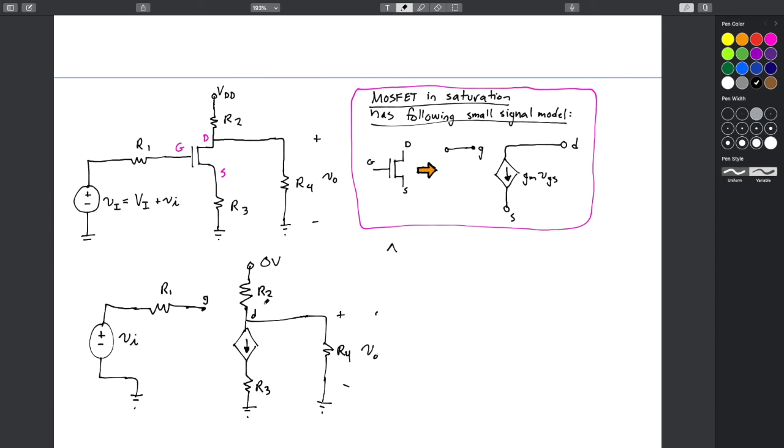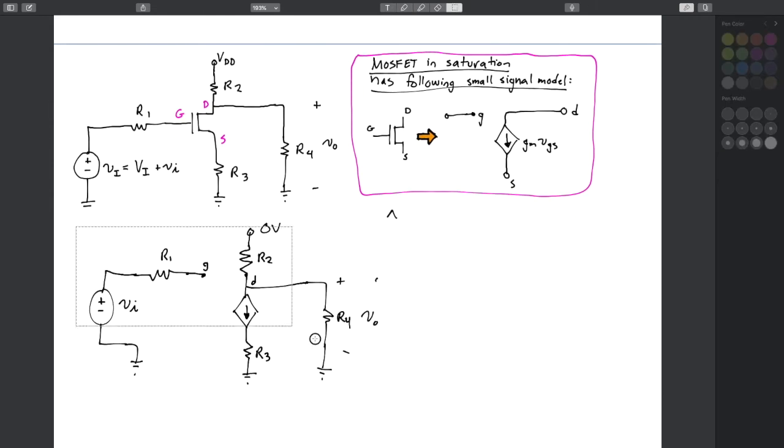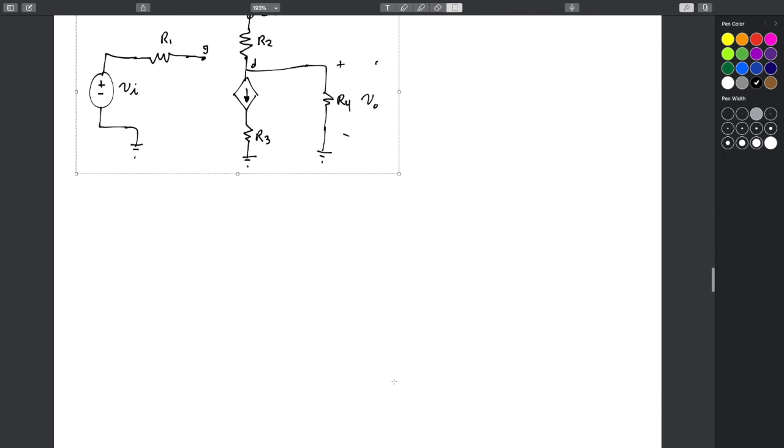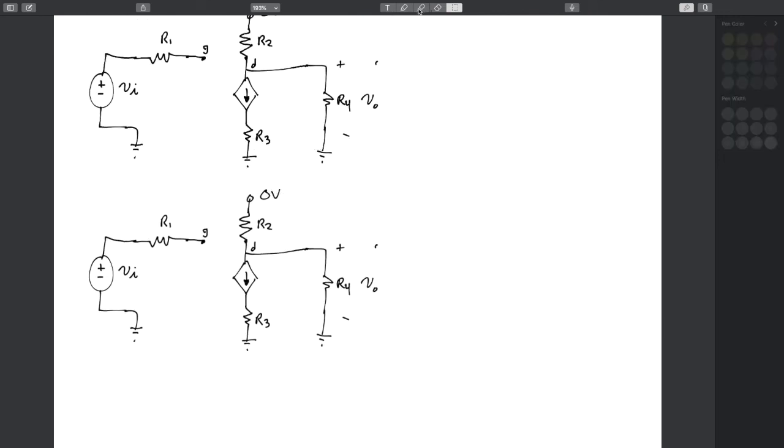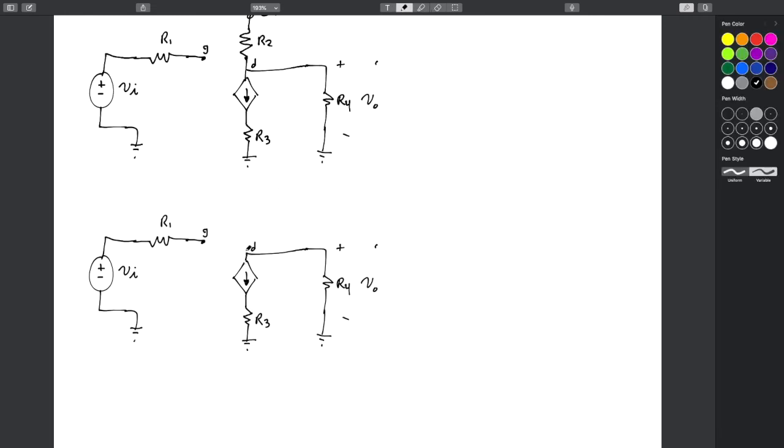Now, because R2 is going to 0, it's the same as it's going to ground, right? So really, we could redraw this circuit. I'm going to copy paste it one more line down here and delete some stuff to make what's going on clearer. And then what other things can we simplify if I'm looking at this? Sorry, I should have made this the source just for reference. And of course, I should have also noted that this is gm vgs. What other things can maybe be ignored?